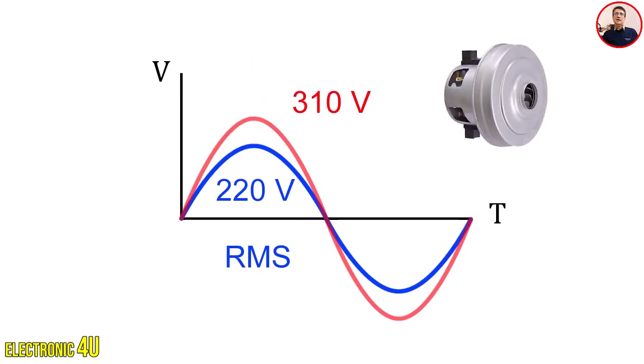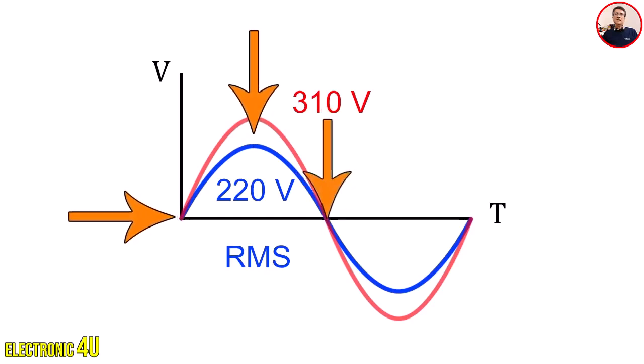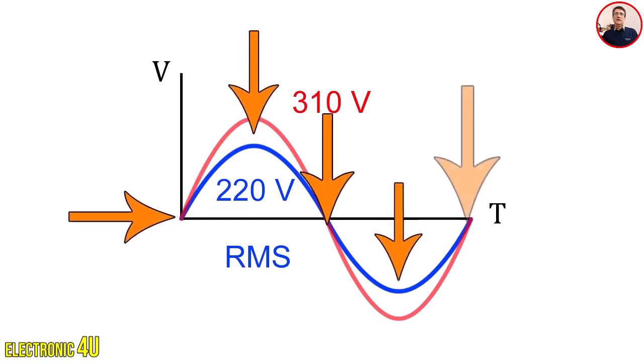To control the power delivered from this voltage to the load, which could be a motor or a lamp here, using a triac, we need to specify when during each half cycle the triac should turn on. The AC voltage starts from the 0 point, rises to the positive peak, returns to 0 again, then enters the negative half cycle, reaches the negative peak, and returns to 0 again, and this cycle repeats.